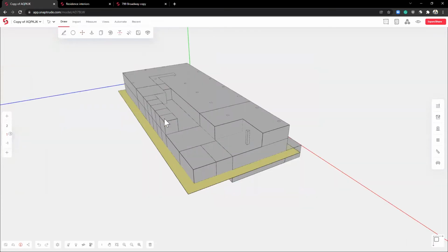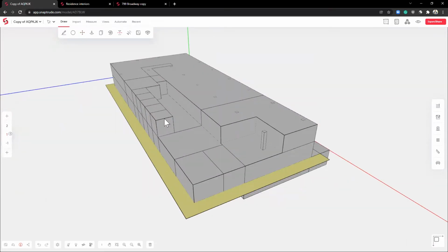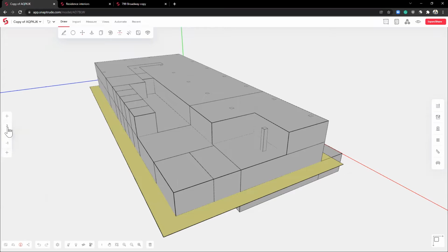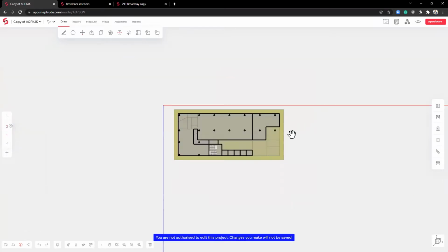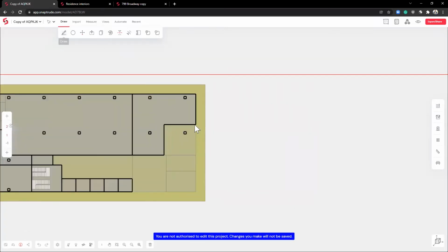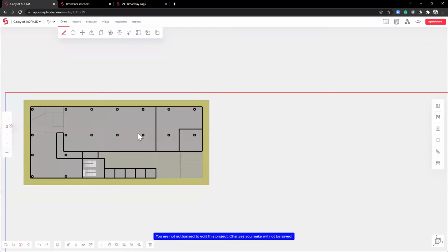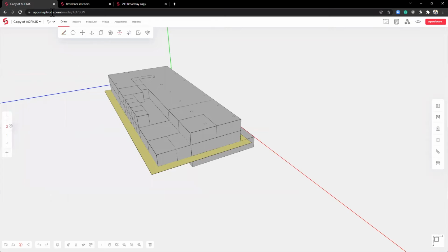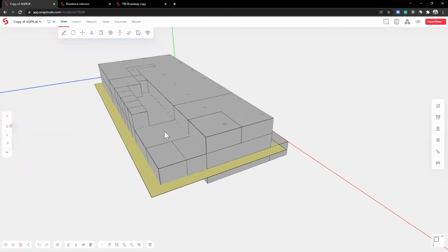And since it's a BIM tool, 2D and 3D just go hand in hand. So I've got the 3D version of the massing study always with me. Let's just quickly go around to the second floor. So the lower floor is shown as a reference, so the snapping can happen much better. So you're not just doing rough massing, you're actually doing fairly accurate stuff. So you don't compromise on the quality of the model and the drawing that comes out of it.